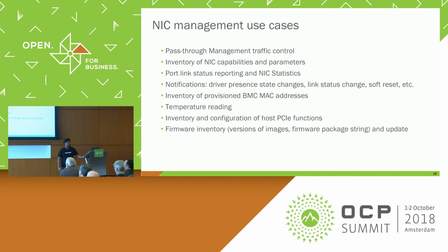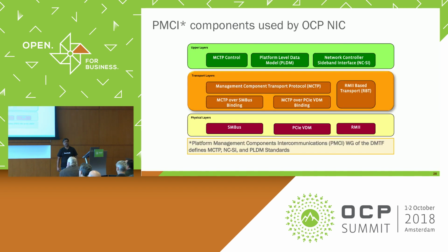But there is no need to invent protocols for how to manage it, or decide what kind of specification to give to the OCP NIC vendor. There are well established standards in the DMTF called PMCI, platform management, and it defines the physical level, transport level, and the command level. As long as the OCP NIC supports these models, we can easily manage it, no matter what kind of OCP NIC card or which vendor makes it, as long as they comply with this standard.